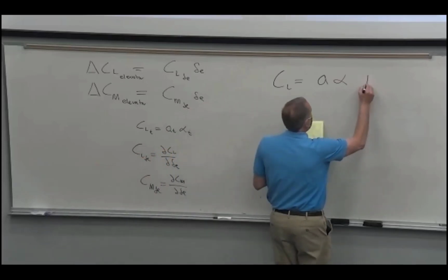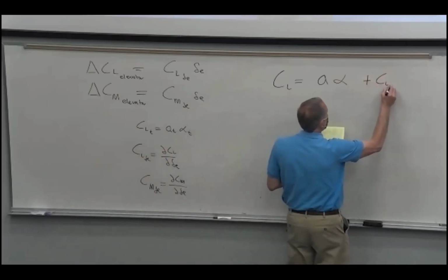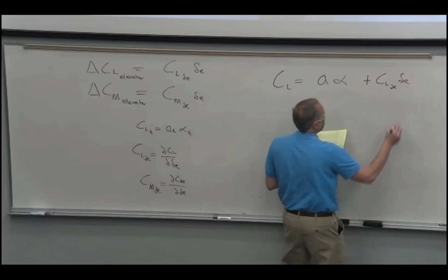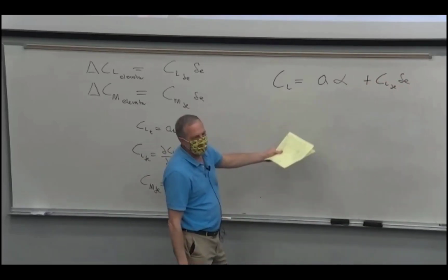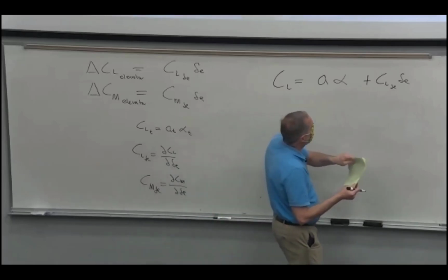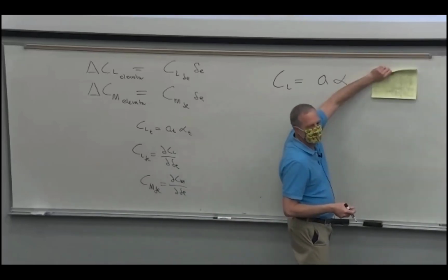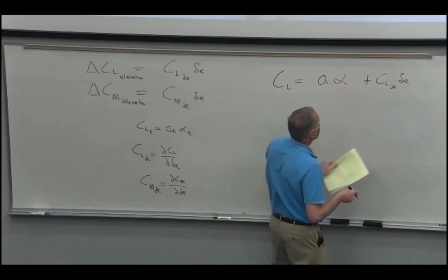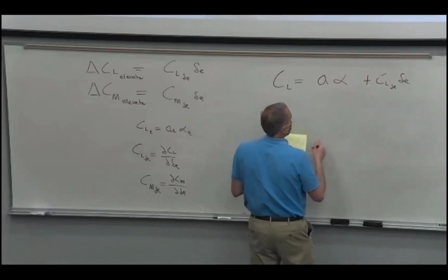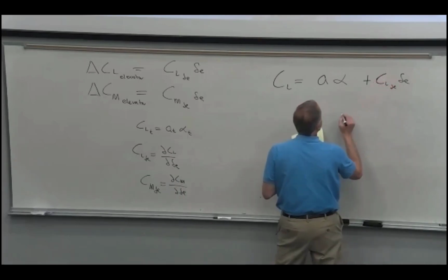And so now we're going to add in an elevator, and we do that by adding that extra delta CL. So that's our new formula for the lift. If we have no elevator, elevator is 0, that goes away and we're back to what we had before. So this is the extra part due to the elevator, and part of the elevator rubbed off on my paper.